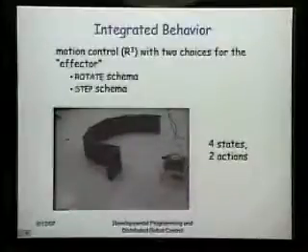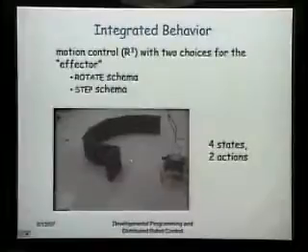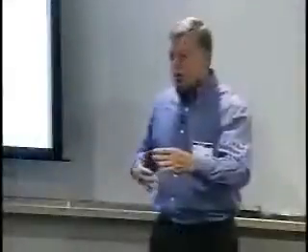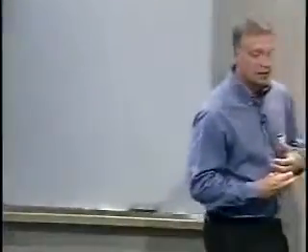I think I'll play it again. Yes, there's a forward-looking IR bumper. And when it sees an obstacle in front of it, it maps it into a configuration space. And then a new path goes around it. And then it's always trying to follow the path that exists with rotate and translate. So there is additional sensing. There's one additional path planning controller. And then the macros that existed already are trying to figure out how to get to those places.